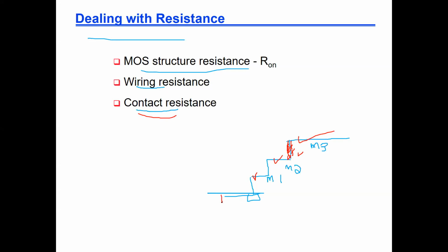And then also the transistor itself has a channel and the current flows through it. So anything that has a current flowing in it as a material will have a resistor. We'll call it R on. Anytime I have a transistor, two transistors for example in this case, between this node and this node, we will assume that I represent them by two resistors. If both are on, we'll have R on 1 and R on 2 between this node and the ground.